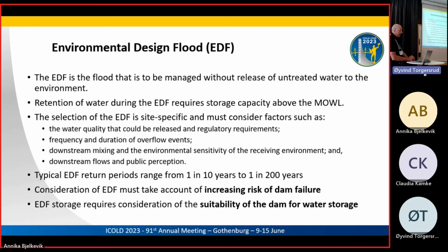The environmental design flood is a bit controversial, but quite normally the water quality in the tailings dams is undesirable for normal release to the environment. So we need to capture that somehow. There's various ways to work it out, and we've given some guidance on how to do that. But it is an area that we probably need to do more work. It's been identified that we might do some more work on that in the future to give some better guidance on how you determine the environmental design flood.